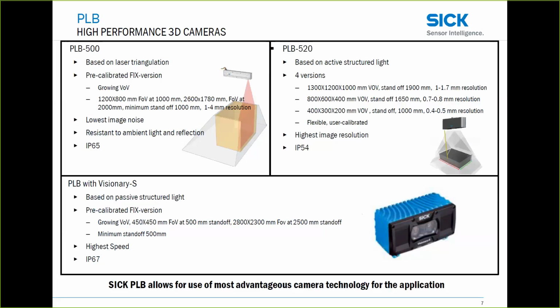So that is a laser triangulation camera. It's going to sweep a laser across the volume of view, and it's going to watch the deformation of that laser with the camera that's inside of it. So again, that's what we're working with today. This one has a very big volume of view. It's a 1 meter standoff, and then you have a 1 meter volume of view below that.